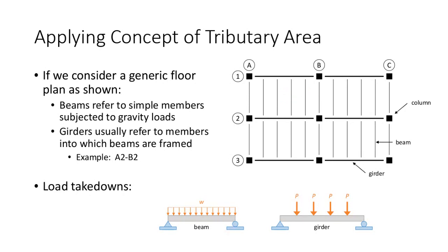Well, I need to erase that. I propose that that floor beam is responsible for this area. Okay, and that would be the tributary area for that floor beam. Why is that? Because as soon as I go outside, as soon as I'm like right here, then the other floor beam takes over, right? So that would be the tributary area for this particular floor beam. Now, as Mr.